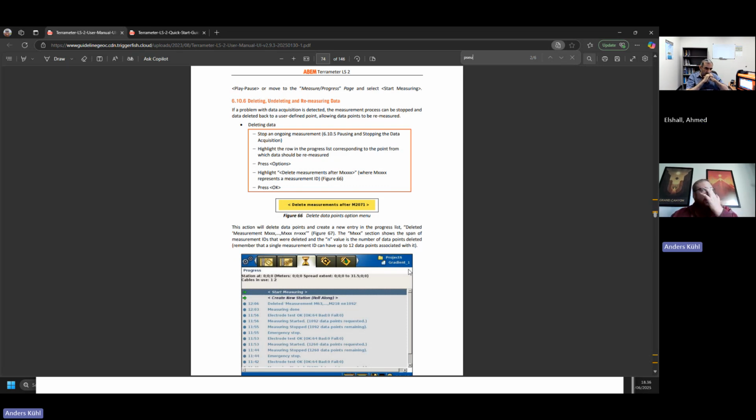In Denmark, there's almost nothing vertical, so dipole is not that useful, since dipole is really good for vertical structures. In our case, we have sand and clay on top and then limestone at the bottom. Gradient does a good general job; it's a good generalist. And dipole can give extra information.